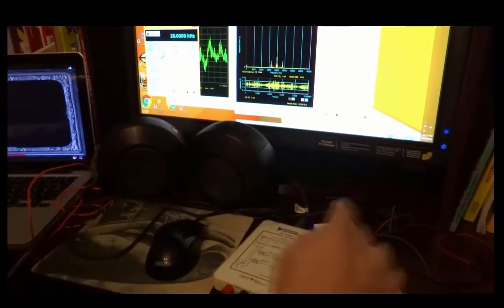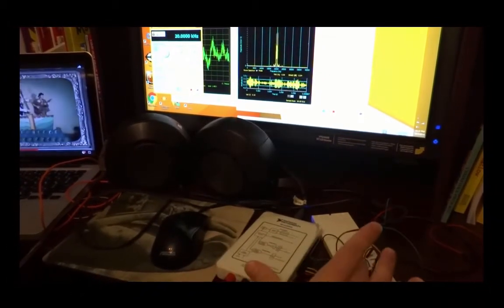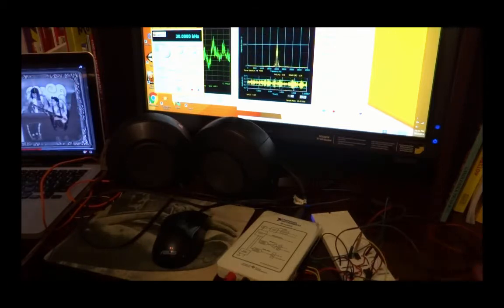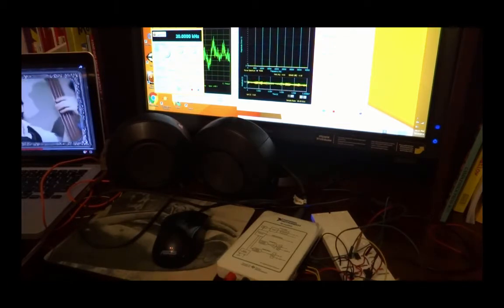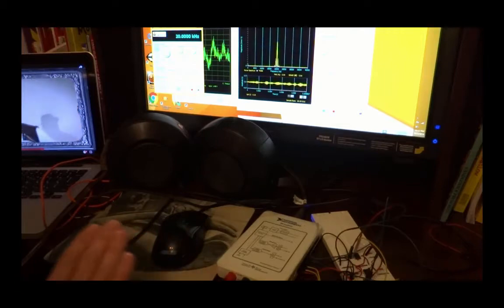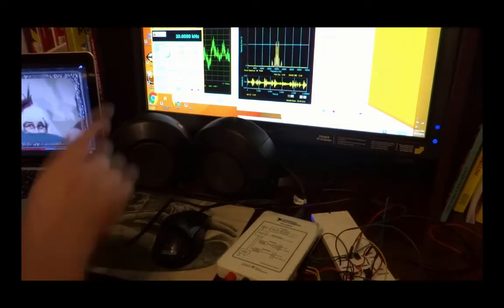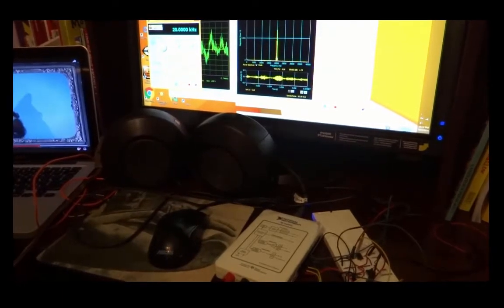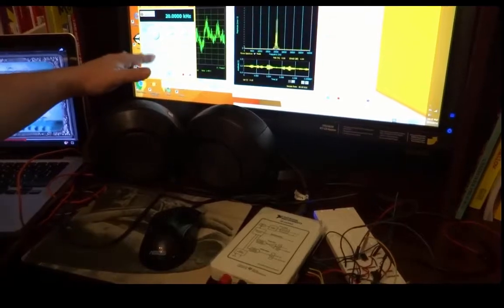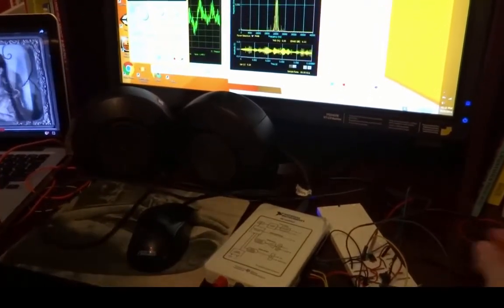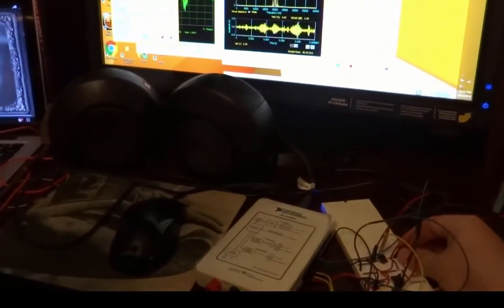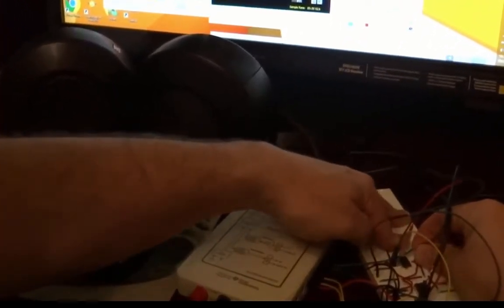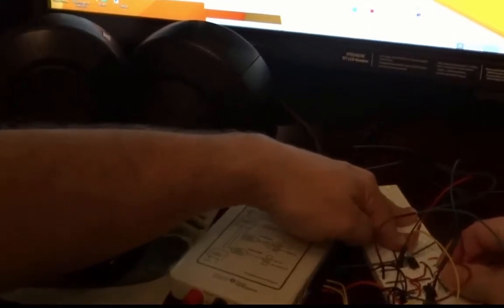So we're going to take this signal, run it through the second integrated circuit here, we're calling it ICB, and all it does is it's another modulator. It essentially takes the modulated signal here, multiplies it by another cosine of the same frequency, and in fact it's the same cosine coming out of here. So let me switch both what we're listening to and what we're looking at to the output now of that second multiplication stage, the demodulator. So I'm going to stick that down here.